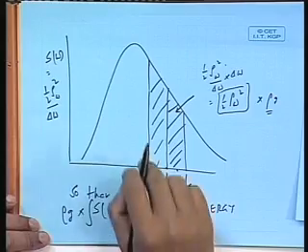The purpose of drawing this curve is that it is nothing but an energy distribution, such that the area under the curve represents the energy. Always rho into g is a constant, and you do not want to deal with that rho g because it is not a nice number, so you take it out as a constant. So this is a very important concept: you are actually plotting essentially the square of the amplitude divided by bandwidth, because you cannot get waves exactly at a particular frequency.